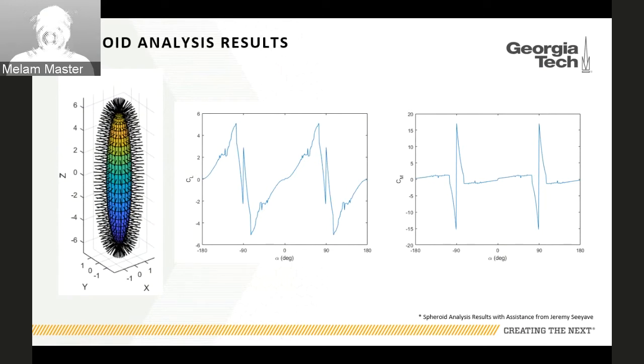As you can see, there's a discontinuity at negative 90 and 90 degrees. We initially thought this was due to an error with the arc tangent, arc sine, or arc cosine being undefined or infinity at certain values. But when we fixed that, we still had the discontinuity, so that's being looked into. One of the things we think is the problem is that the research and CFD data we have is not complete across all angles of attack. We only have it for a few angles of attack, and so our line fit coefficients aren't realistic because we're getting non-physical results in our data.